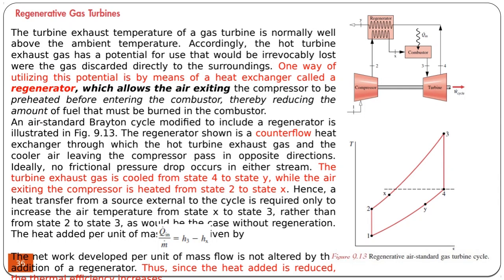What happens is, instead of just rejecting the heat here, we can use a heat exchanger here, which utilizes the waste heat to heat the air at the exit of the compressor, because the air at the exit of the compressor must be heated in the heat exchanger here.